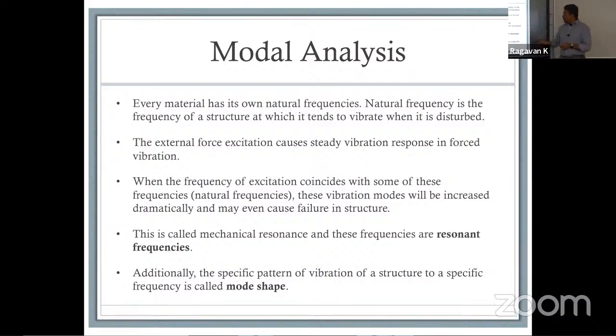So if you look at specific patterns of vibration, what you get from a very specific pattern of vibration are referred to as modal shapes. If you have done NVH analysis, let's say on software like ANSYS or COMSOL, you might realize that they have these modes where they show you the shapes of deformation that you get in an electric motor, right? The deformation is not that the machine is actually shaping out into an egg. These are much smaller deformations that create that vibration.